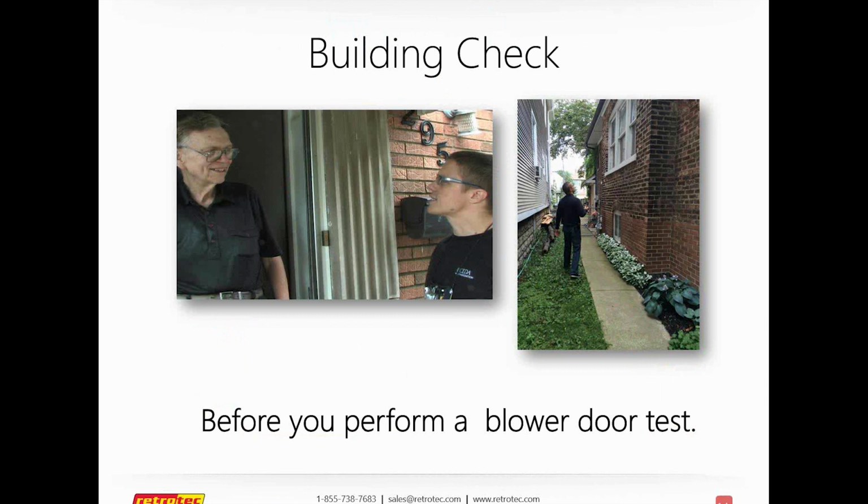You might be surprised to know that probably the most important thing about a blower door test has nothing to do with the equipment. It has everything to do with the process. And the most important part of that process, as with most processes, is that it starts out right. The first thing that you want to do is a building check.